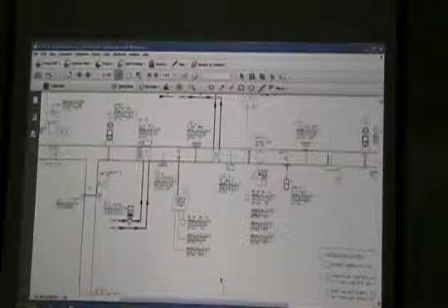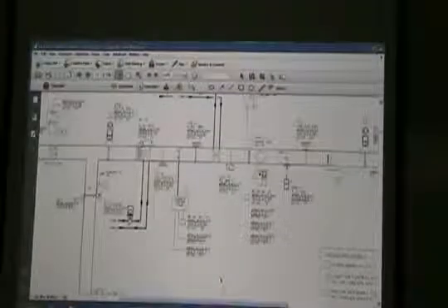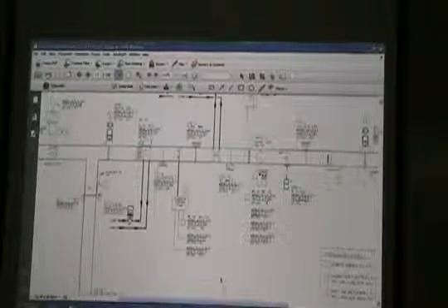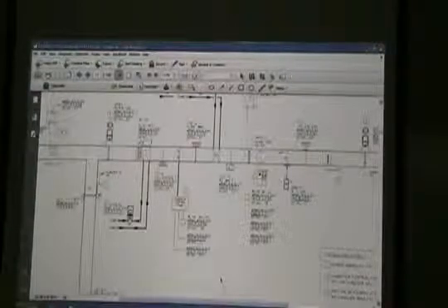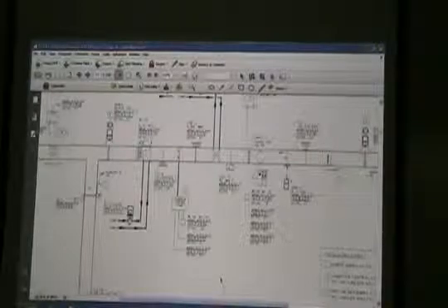This is not really drawn correctly. Probably what the air handling unit looks like, I've got a coil, and I've got 2 sets of dampers. So this is the air handling unit. Probably, we talked about earlier, face velocities on coils. We talked about cooling coils because of the moisture carryover capability. We want 500 feet per minute.